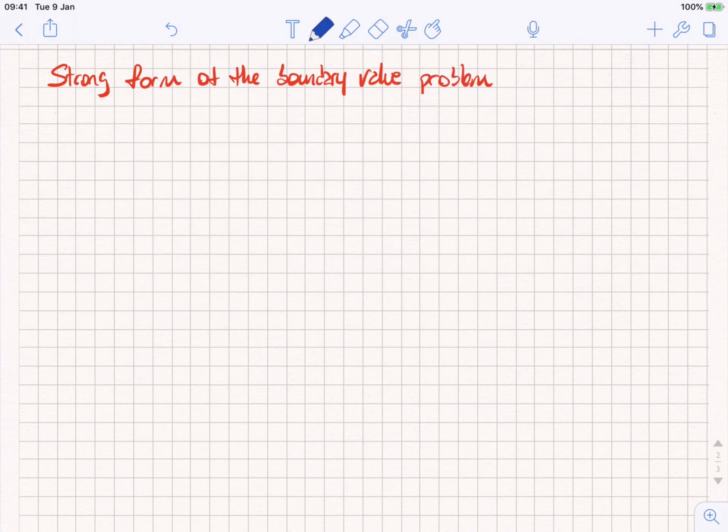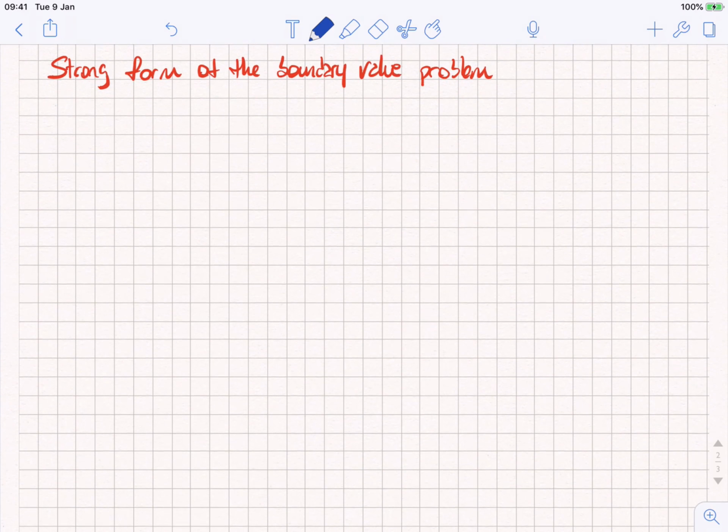So normally you will also find this type of terminology in papers. You're going to say, well, first I need to define the quantities that are going to be involved in my equations. So given E, which is the Young's modulus, whose domain is omega bar, the closure of omega, to the reals, this is just very simple notation to say that this E is defined on the entire domain plus the endpoints, right? And it's just a scalar.